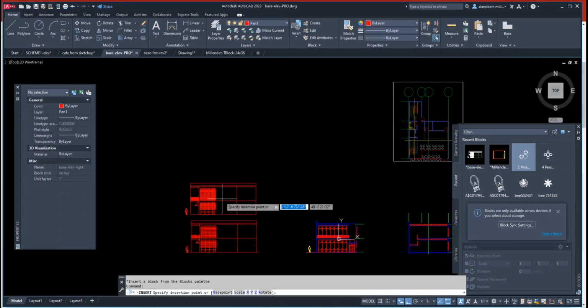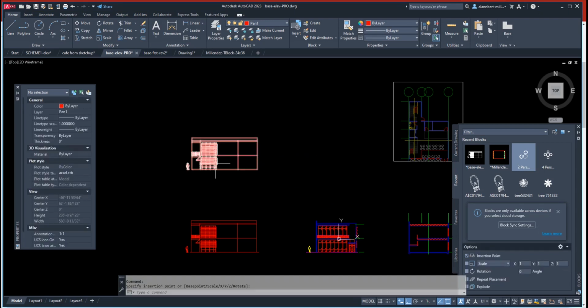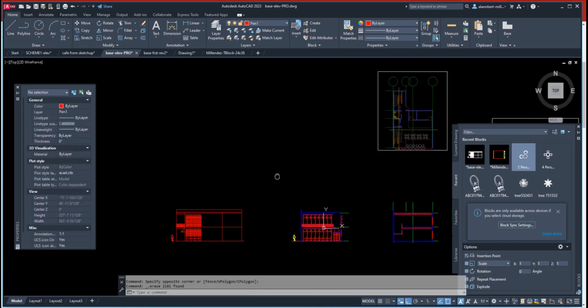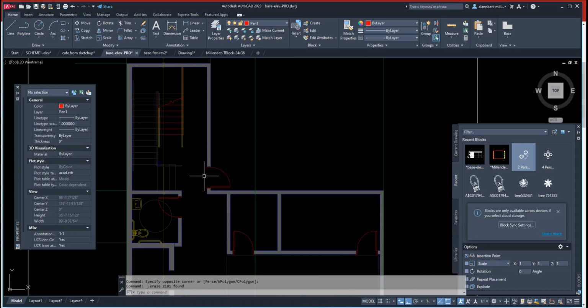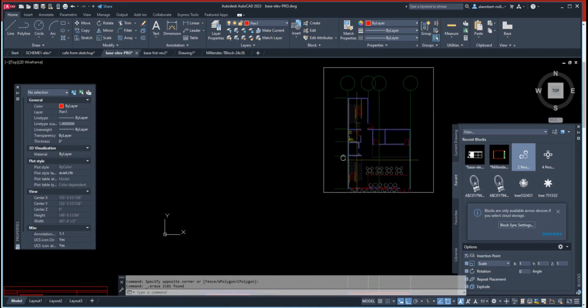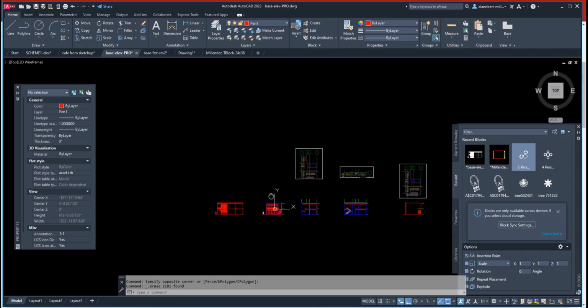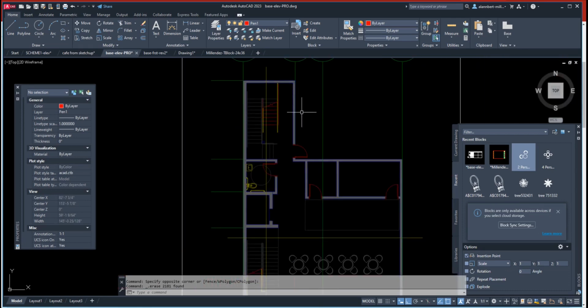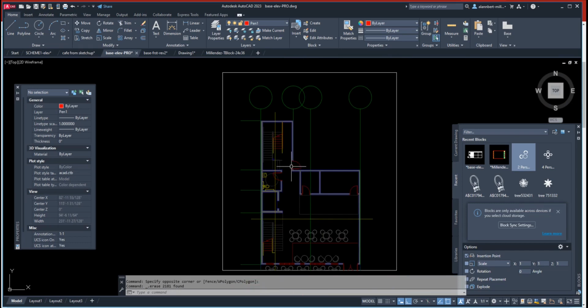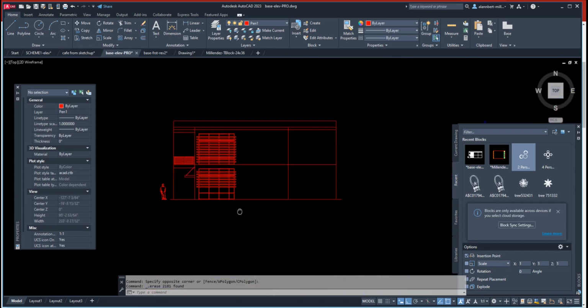Okay, I already inserted here. When you insert it, this is a whole block, so you need to explode it just like we did before. Oh, and it'll turn white, and then you can just put it into different layers. Okay, so let's just erase that. Okay. Now, if you look at my floor plan has a door here. Okay, somewhere. And because I didn't do that in SketchUp, I'm missing this door here. Okay. If I have any windows on this wall, I would also have to indicate that. But let's just work on this door. It's on this corner over here.